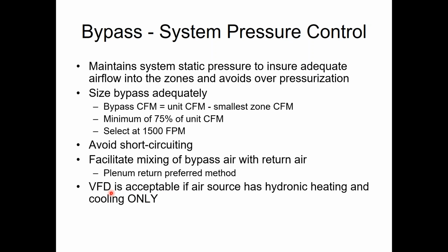You're probably still going to have a bypass damper with the VFD in order to keep these units online when I have small zones calling without everybody calling. Because I'm only going to be able to throttle that VFD down so far in order to keep this unit online, unless I get one with lots and lots of stages, i.e. a VAV style unit, which at that point, why isn't it a VAV project?